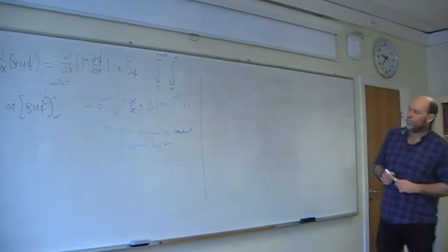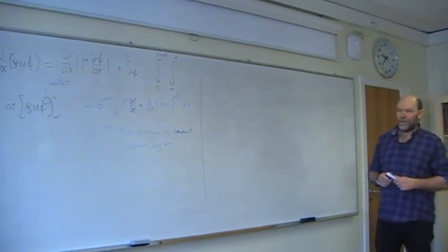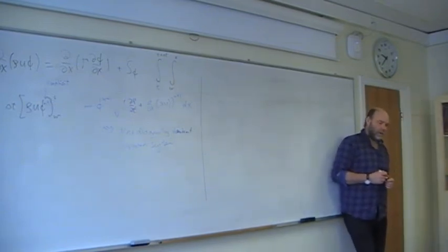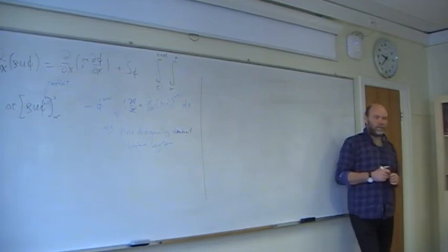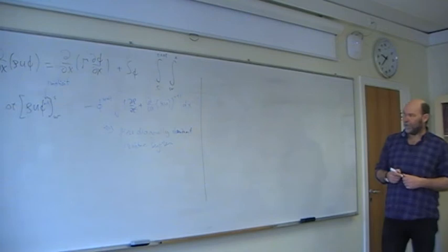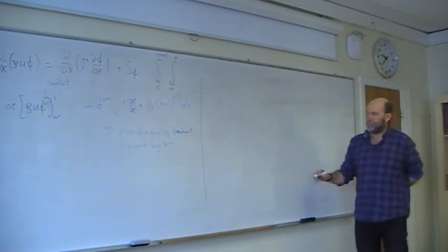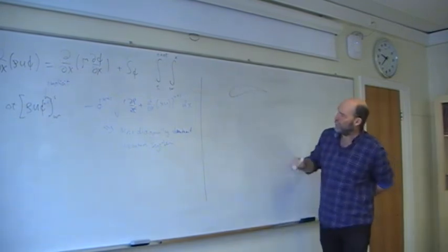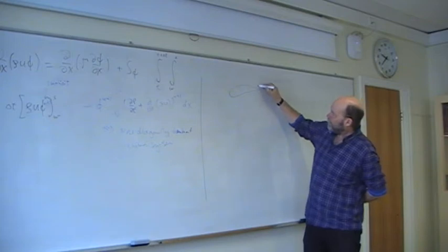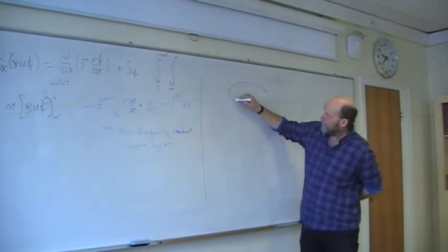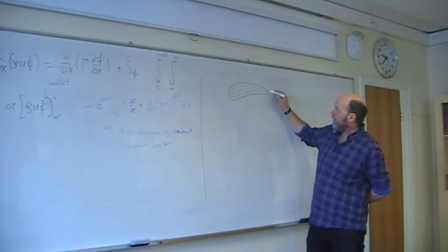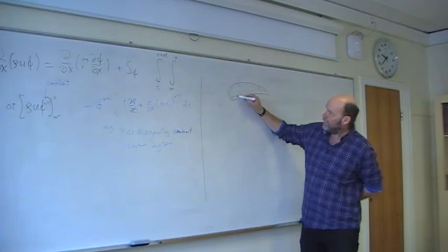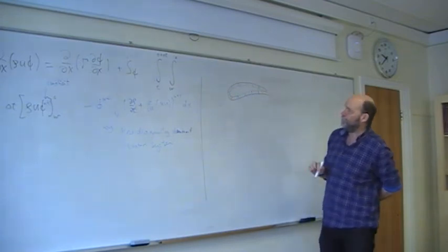But say in general, a structured mesh will be better, faster, more accurate than an unstructured mesh. So if possible, try to avoid unstructured. Can be hard, of course, but for instance, for such a problem, typically what you will do, you will have a mesh layer to resolve the boundary, and that will consist of structured mesh systems like this.